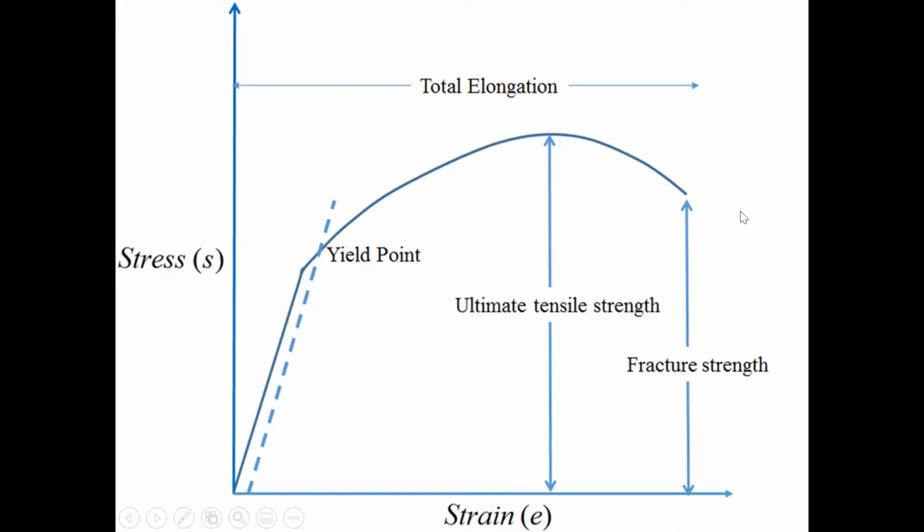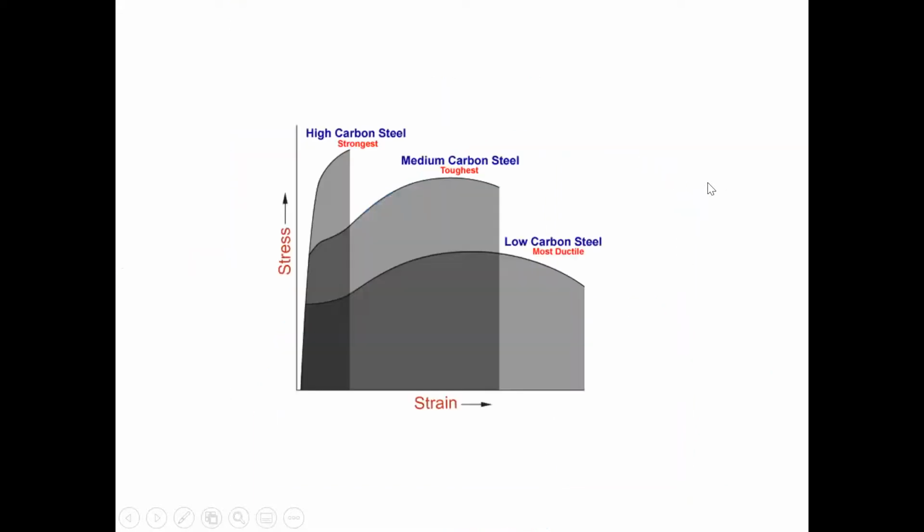So when we do the slow strain rate method, we're measuring this point here very precisely. And this is what we want to know. This point, and we want to know this point. We're not so interested in all of this because we're deliberately breaking the sample because we want to see when it's going to fail. That's the whole point of the slow strain rate method.